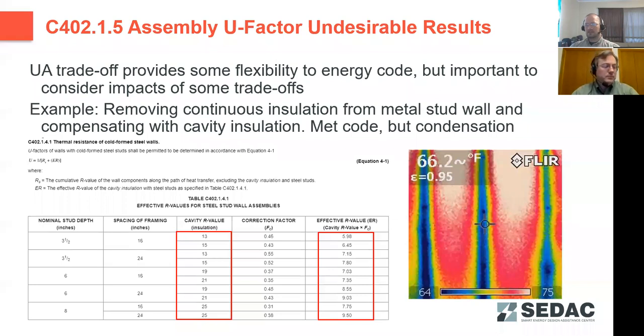And you can see here that each of those steel studs, you can even see the screws going through the drywall into the studs, those really dark blue points. So really important when you're specifying, if you're doing the UA trade-off, to consider thermal bridging in your structures.